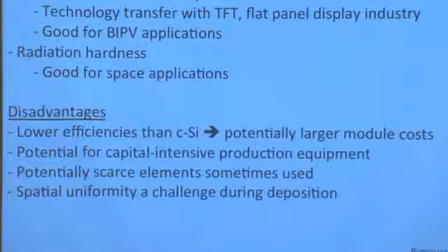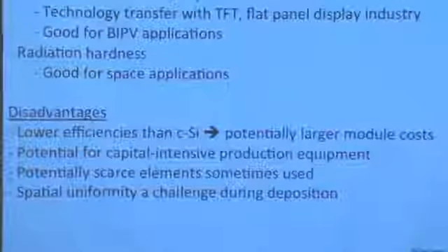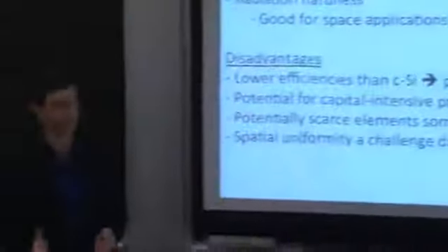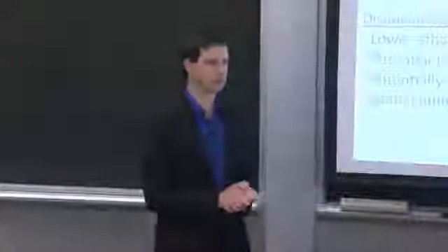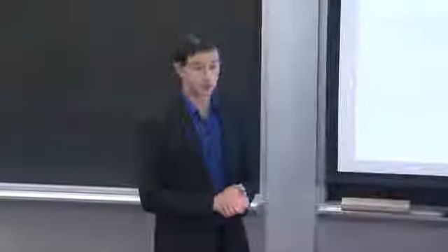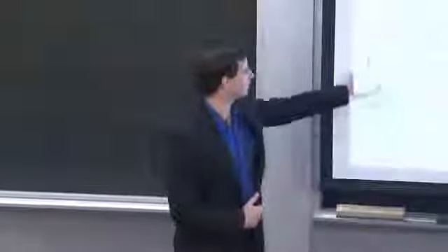So at some point, if you look at the cost of the material versus efficiency, you start entering negative territory. You actually have to be paid. If you're producing like an 8 or 7% module, typically, you would have to pay your customer for them to accept your module. So you really have to achieve a minimum efficiency target to be cost competitive. And as a rule of thumb, that's typically 10 to 12% for today's costs of glass, encapsulants, framing, materials and labor and installation, and so forth.